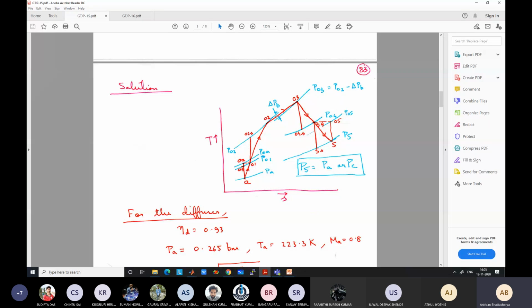So if you go to higher temperatures, the compressor work input increases, and that leads to higher fuel consumption, meaning for generating the same thrust, higher specific fuel consumption and lower specific thrust, because more work is required for the compressor. That also plays a role apart from the momentum drag, inlet drag.